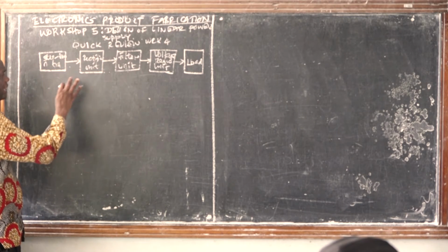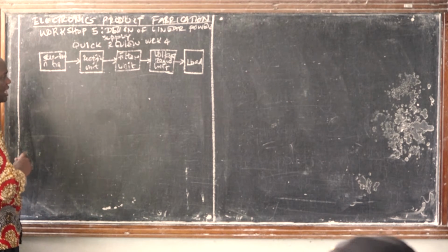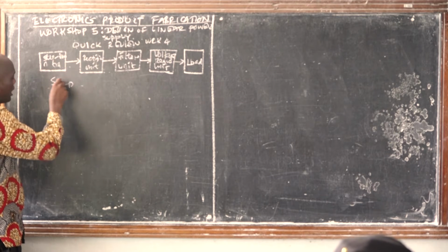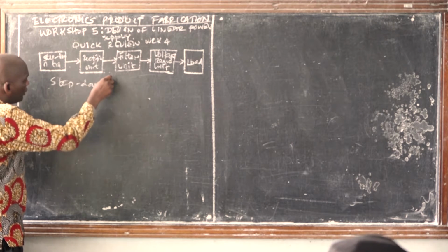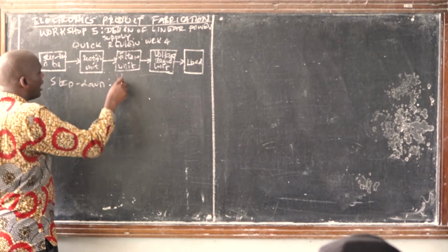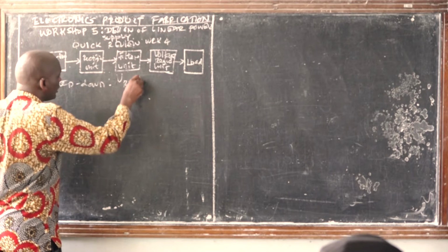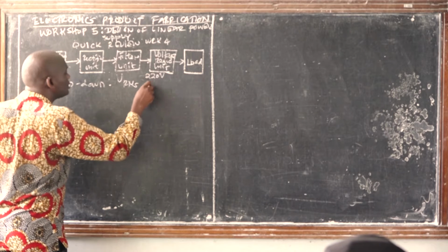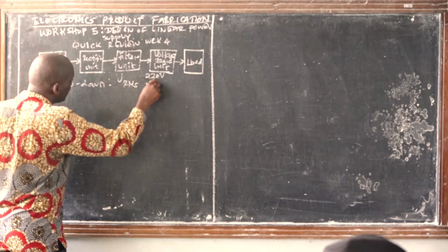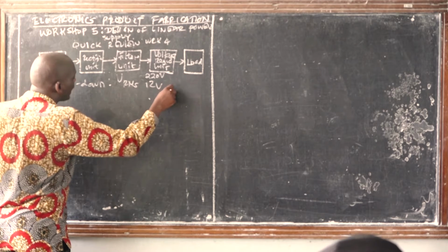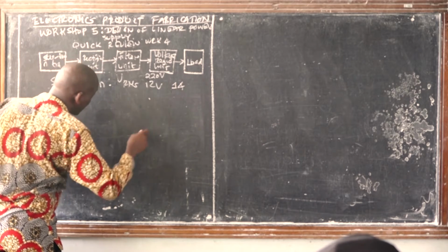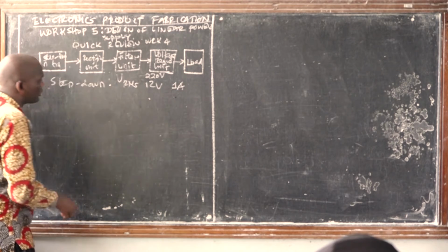Just to remind you, we chose a step-down transformer with the following specification: the input root mean square voltage is 220 volts, and the output is 12 volts. In terms of current, we have chosen a step-down transformer that provides 1 ampere. That's the important parameter.